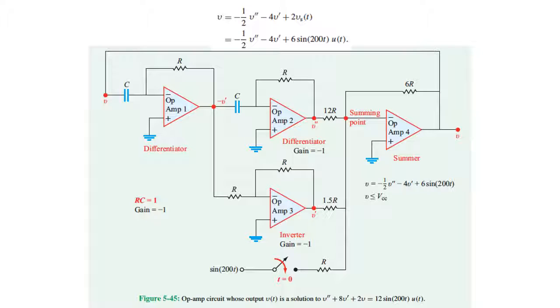So this is going to take a little bit longer. I'm going to try to print this one out. We're going to talk about it piece by piece to try to walk through why this works. But for now, try to see that you can use these 4 op amps to do a complex function like this with two derivatives, a double prime, a single prime, and a weird signal coming into it too, in order to get an output.